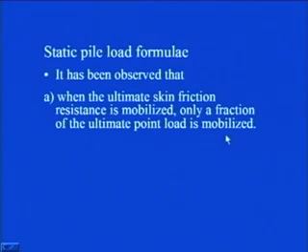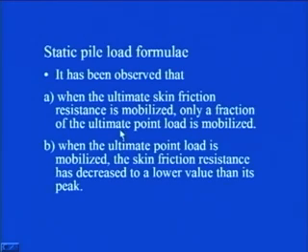That is very obvious, and when you increase the load coming from the superstructure beyond this particular stage, then this ultimate point load will go on increasing. And then the second one is, when the ultimate point load is mobilized, the skin friction resistance has decreased to a lower value than its peak.